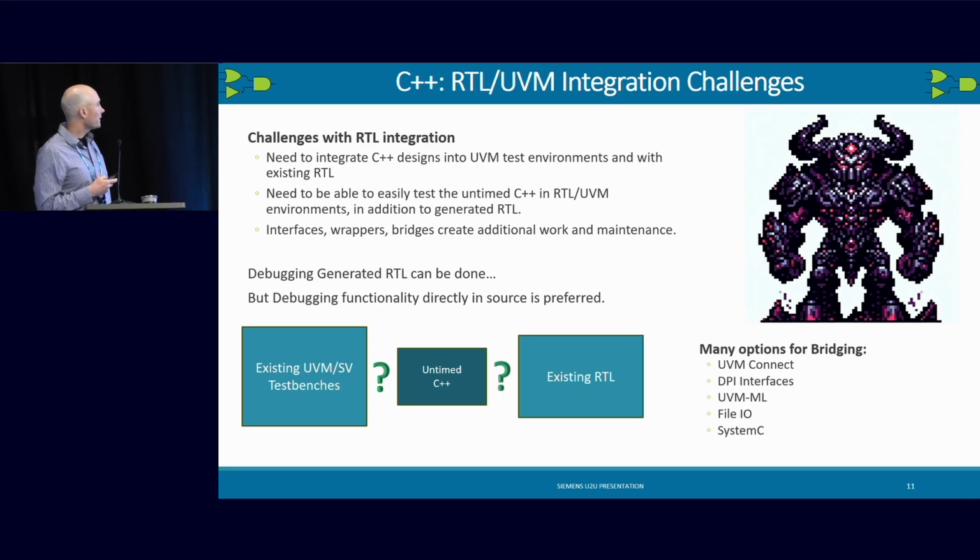At the end of the day, when integrating with these environments, you can use the generated RTL, but in these test environments you want to be able to test your source code instead of the generated RTL, because debugging the generated RTL adds additional work, since you have to back out what the tool did.